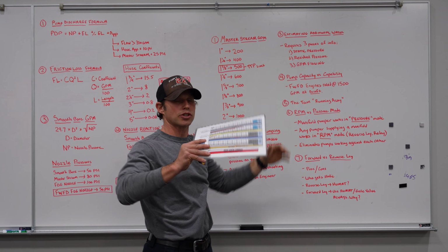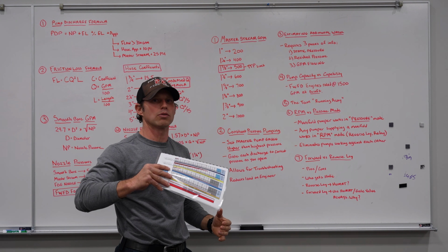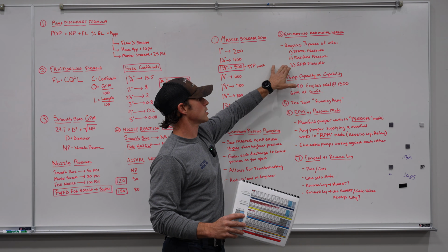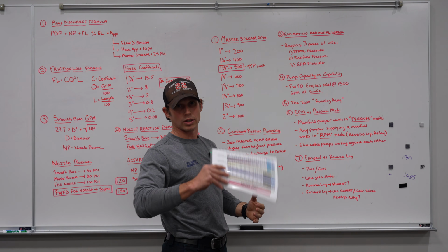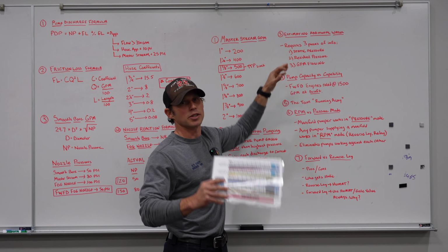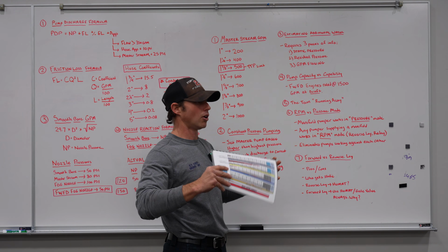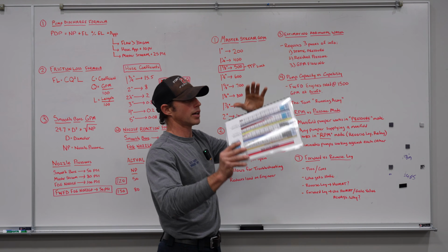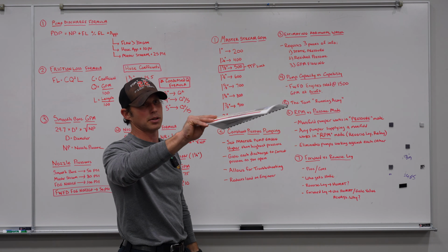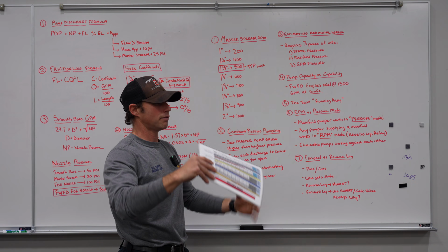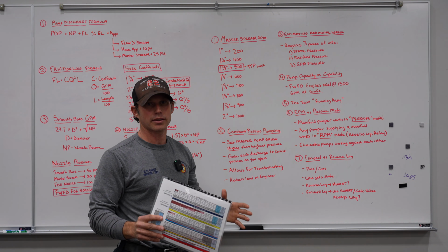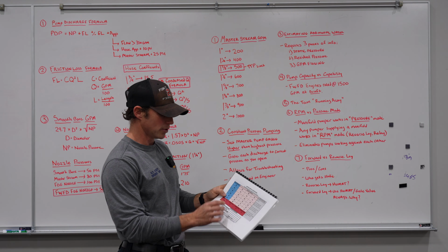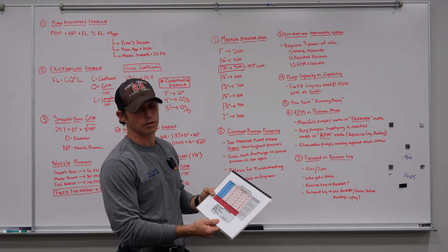Your residual pressure is going to fluctuate based on you opening and closing lines, and also your gallons per minute flowing. So anytime you open or close lines, you're going to either be flowing more or less gallons per minute, and that's going to change your residual, depending on how many gallons per minute you're flowing. So anytime you want to figure this, you know exactly what your static's going to be. Look at your residual pressure, figure out your lines and what you're flowing at that time, and then you can consult the chart here and use this nice chart to help figure out where you're going to flow.